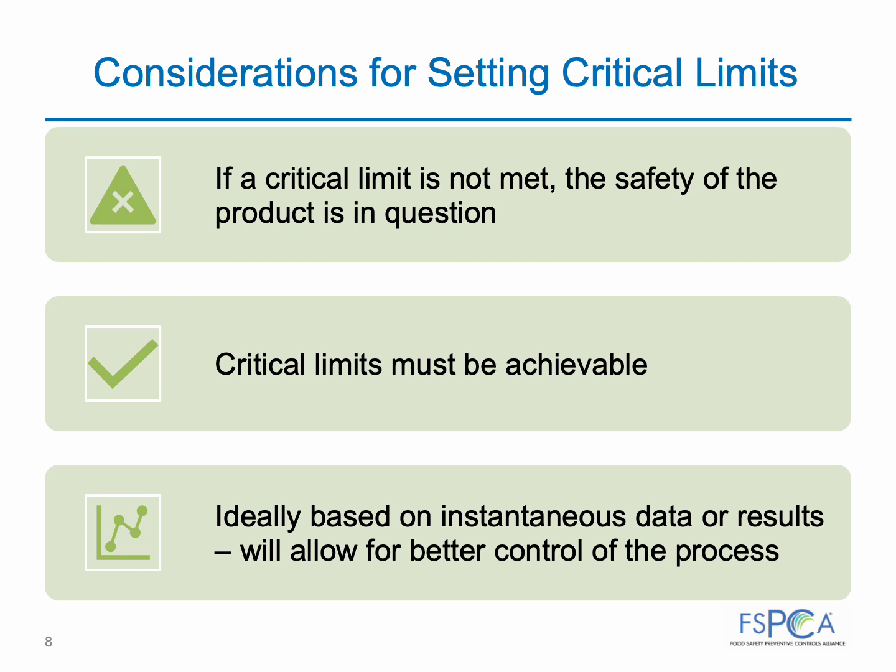For example, processing equipment may not easily maintain the exact value of 160 degrees Fahrenheit, 71 degrees Celsius, so the critical limit would be set at equal to or greater than 160 degrees Fahrenheit, 71 degrees Celsius. This allows the CCP to be achieved and gives the option of exceeding it to enable being more conservative or to operate at a higher processing limit.